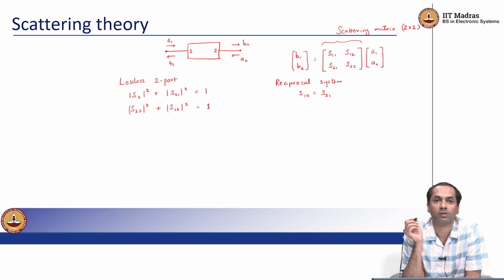So the first statement is saying that if I were to inject some power in port 1, and I were to send no inputs through port 2, the energy that is coming into port 1 would have to redistribute itself into port 1 or 2. That's the only 2 options for it. This is what a lossless 2 port network is. There's no mysterious energy being lost in this wave network.